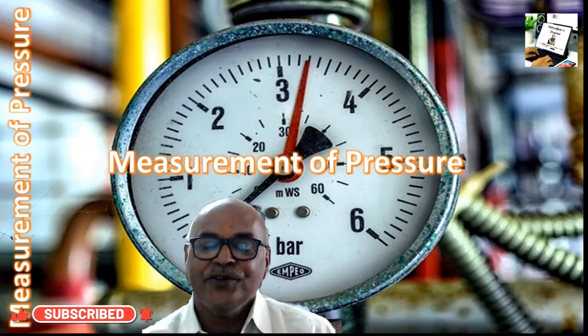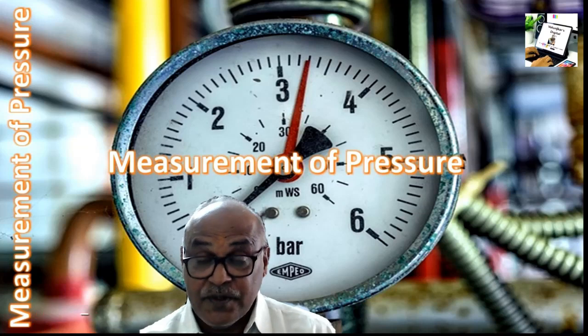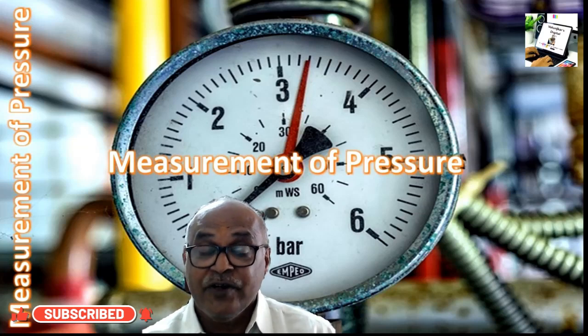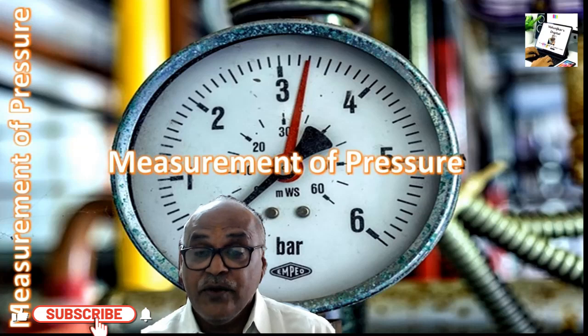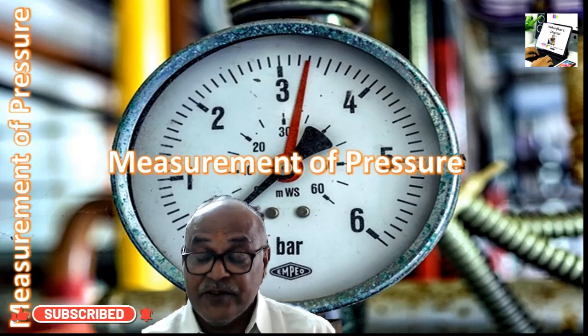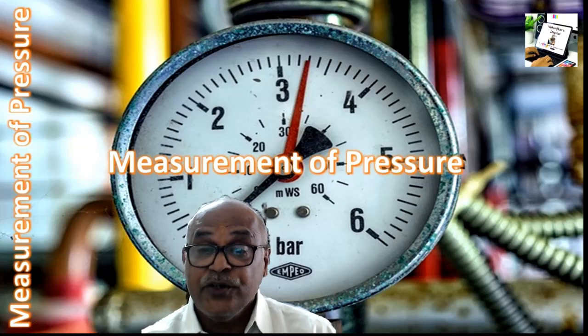Then we have also studied the differential micromanometers and the differential inverted U-tube manometer. Inverted U-tube manometers are very sensitive, and when we want precision in level difference or in pressure difference, in that case inverted U-tube manometers are used.